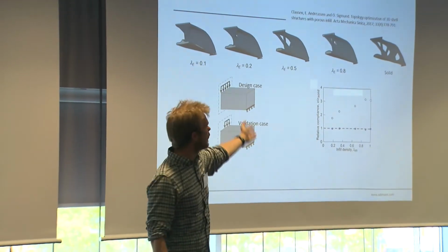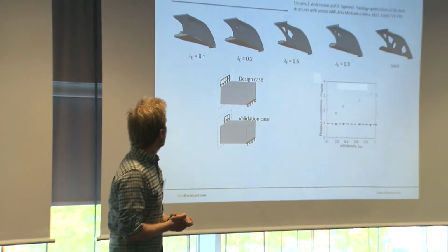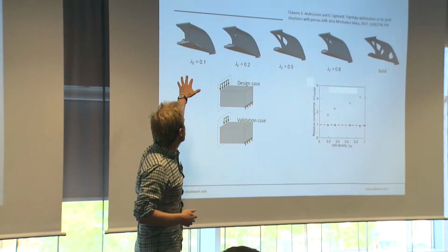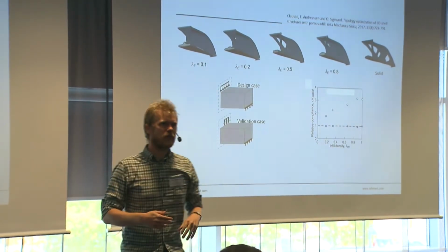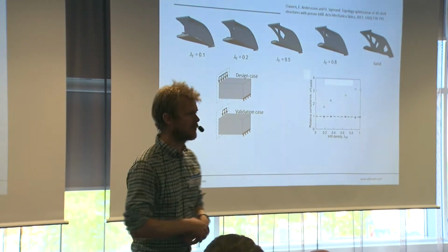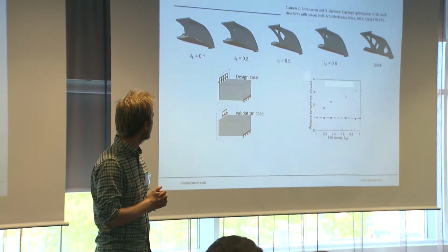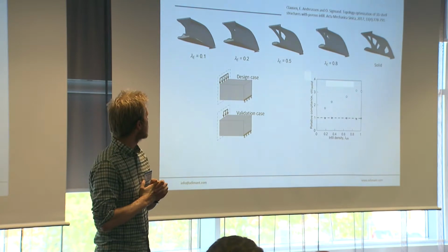So there's the exact same mass going into this part. And what you see is that we get some lattice structures inside the volume. So we're a little bit back to some of the shell and core design concepts you see in Magics and Netfabb. And why would you want to do this?